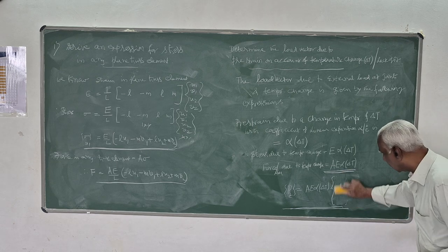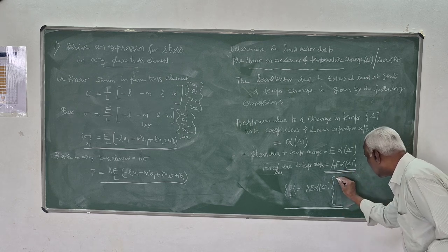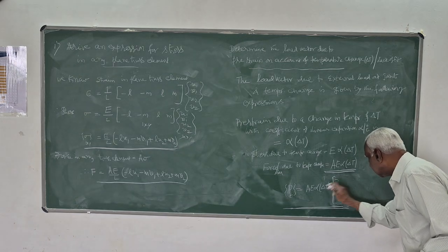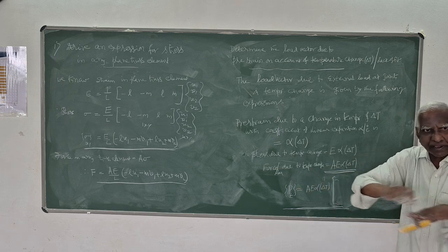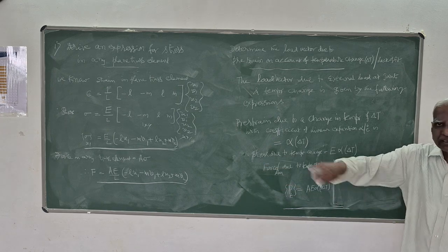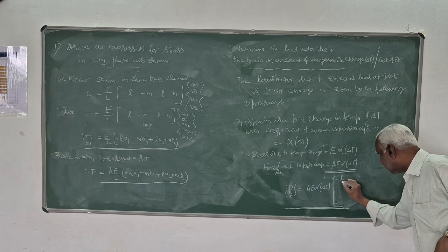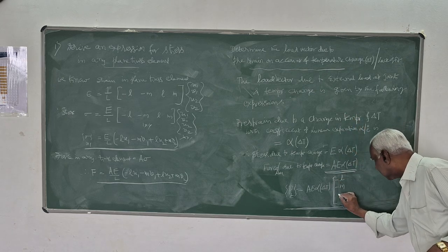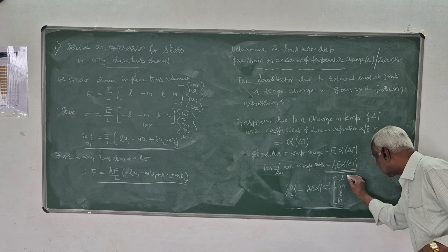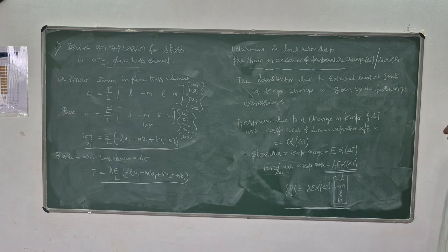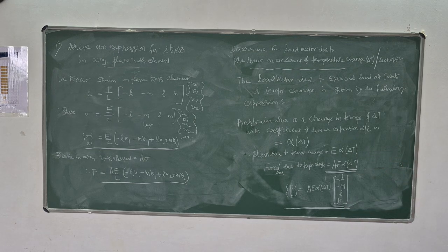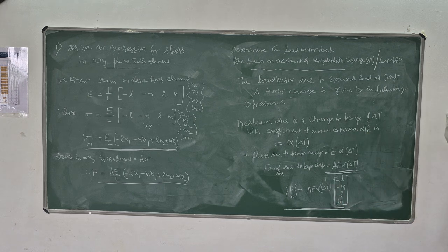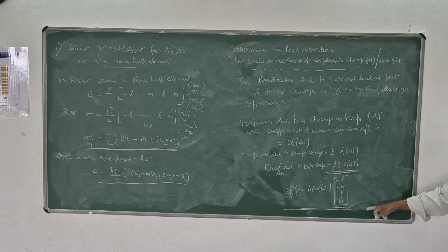It is minus L, minus M, L, M in global coordinates. Temperature change is in one direction along the member. For the nodal points, you have to multiply this by minus L, minus M, L, M, corresponding to the nodal vectors in global coordinates.